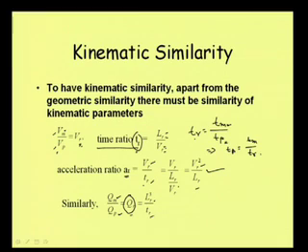So, if we have the time ratio value and length ratio value, then we can have this term Q ratio, and then if in the model we are getting a Q, from the known value of the model we can get the value of what it will be in the prototype. Or in the reverse way, suppose we know that the actual object in the prototype will have this much discharge, then to conduct the experiment, how much discharge do we need to put there?